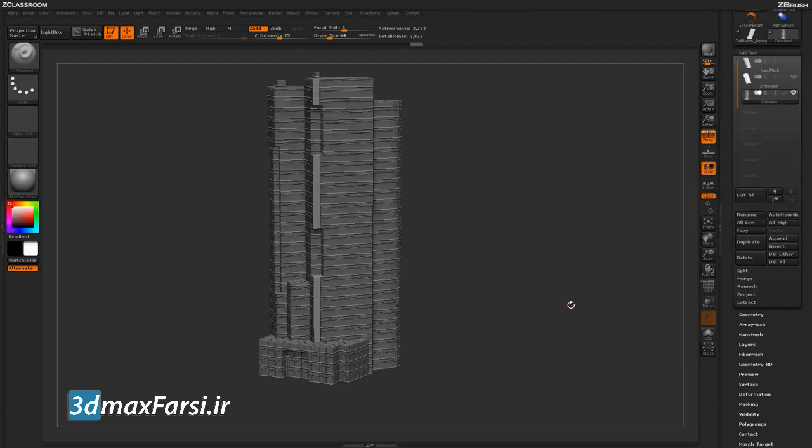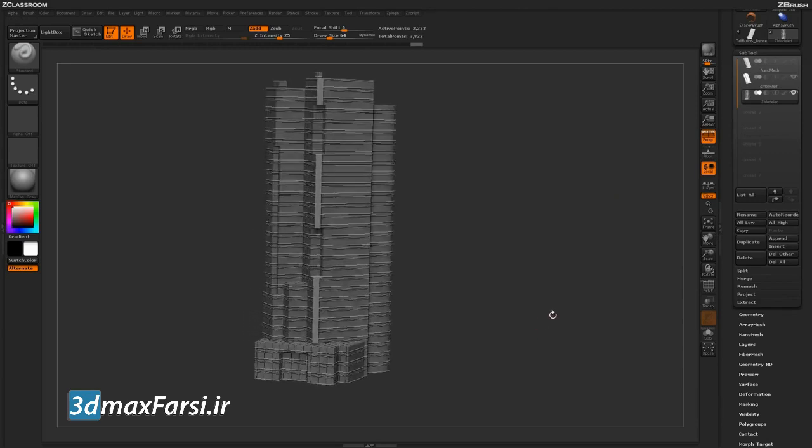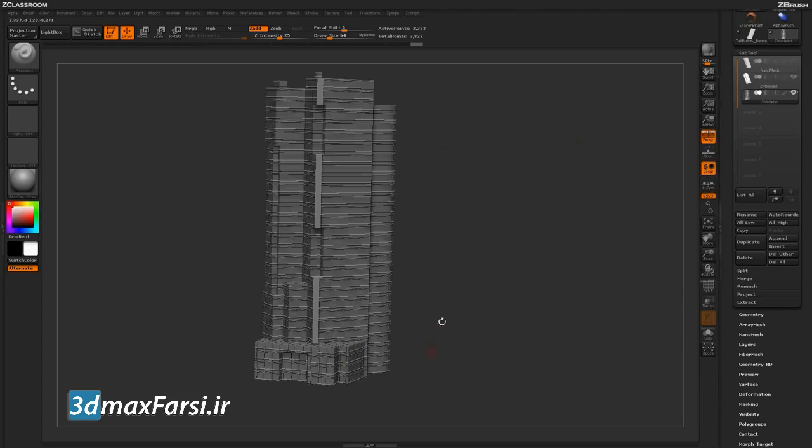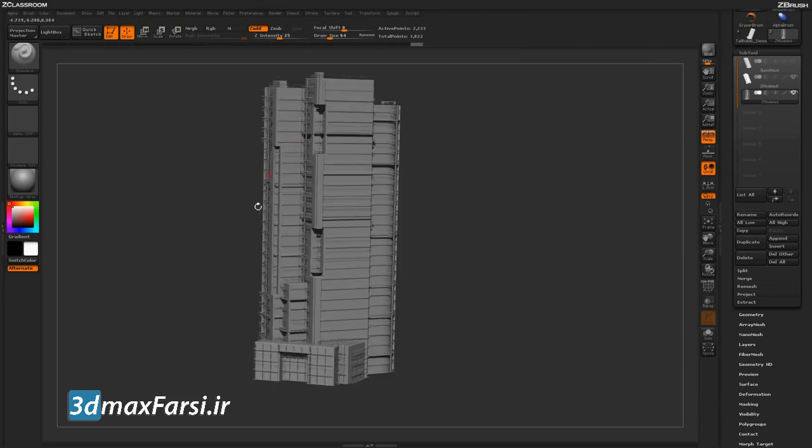Let's just turn that on quick. And now I have both these guys visible on screen here. So now if I render with BPR, this first model, the original one, is going to just render like normal. And the second one, with that surface noise applied and the offset value set, is going to generate on top of it. So if I click BPR now, I'm now generating this as my actual building. So this is looking really nice for the amount of time it took to generate this process.